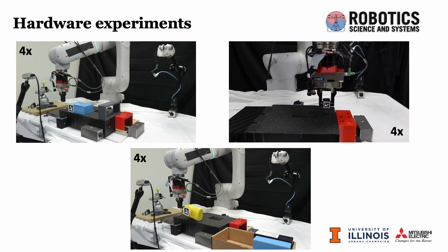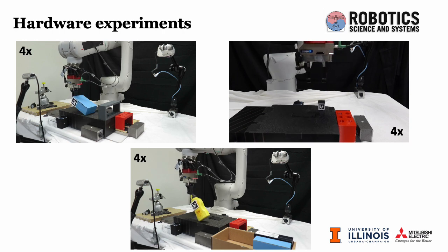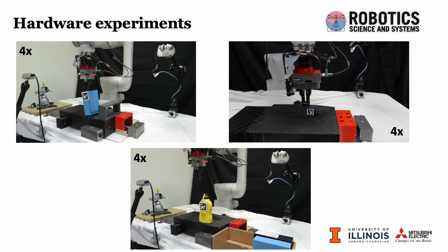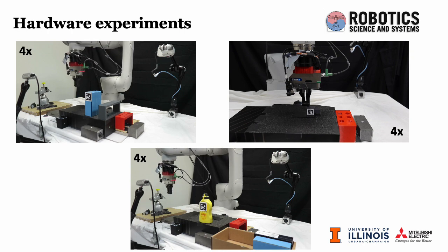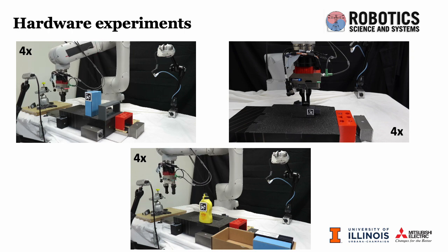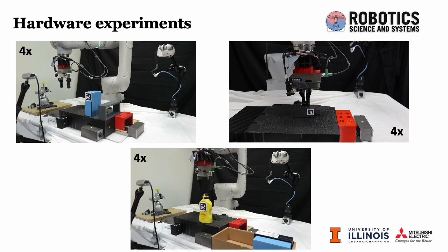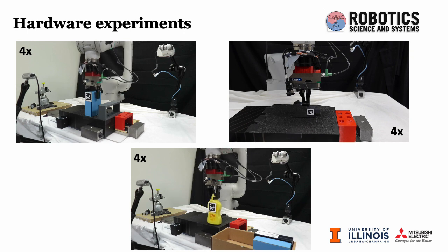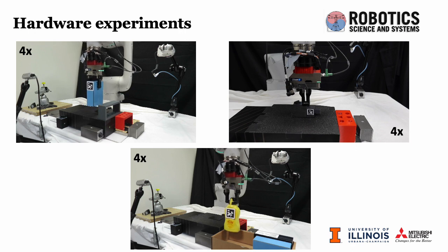Hardware experiments are performed to evaluate the planned trajectories. A Mitsubishi Electric Assist industrial position-controlled arm with a force torque sensor mounted at the wrist of the robot is used in the experiment. The default stiffness controller of the robot is used to execute the planned force trajectories. We use April tags to track the pose of the object, and when a single-mode manipulation trajectory is completed and a new manipulator contact needs to be made, the object pose feedback is used to initialize the new contact.